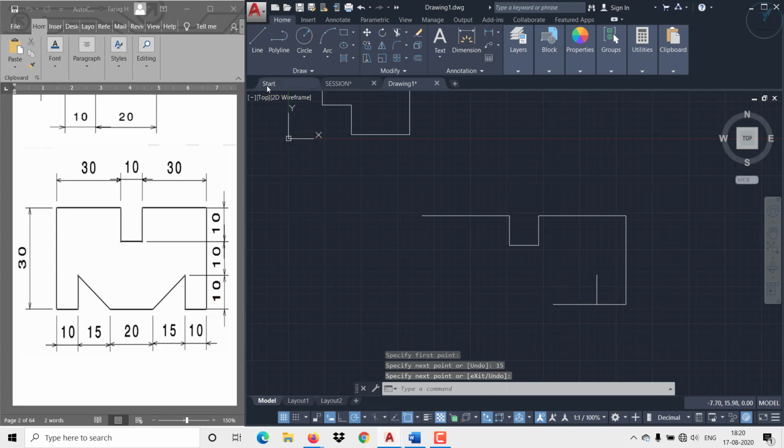So click on this line command, so come over here from this endpoint to this endpoint. So we will continue, then we can remove that. So this distance is 20, enter. Same, this is inclined, so we can't make, so just press escape, then I can just select and delete this one. So then I can start from here, then I can connect it like this way.